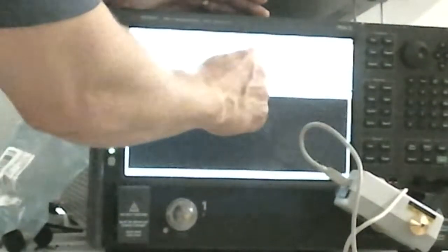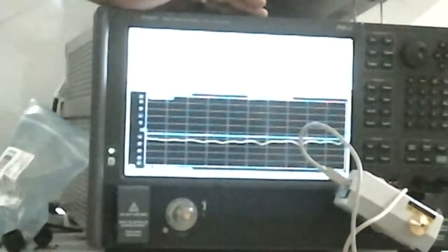So if you know you're going to do a very wide measurement, and then you might want to narrow down, so maybe you're looking at an antenna and you want to say it's somewhere between 1.5 and 2 gigs, and then I say, okay, now I know it's around 1770, and I should narrow down and look at maybe 100 megahertz of bandwidth because that's what I designed. Then I can do that as long as I started with a lot of points. It's okay as long as I keep that frequency spacing consistent, right? If I change the frequency spacing, I'm going to get this interpolated calibration. And sometimes if you don't use enough points, or you use too many points, it can cause some issues that way. So I'm going to do the measurement here. It's going to change through the different loads.